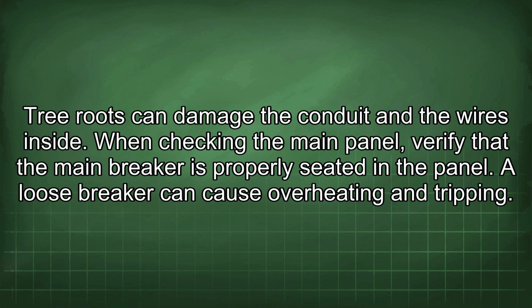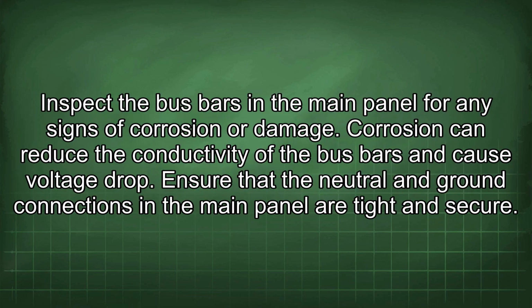When checking the main panel, verify that the main breaker is properly seated in the panel. A loose breaker can cause overheating and tripping. Inspect the bus bars in the main panel for any signs of corrosion or damage. Corrosion can reduce the conductivity of the bus bars and cause voltage drop.